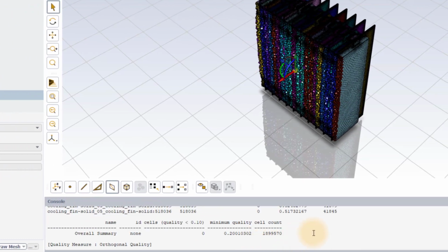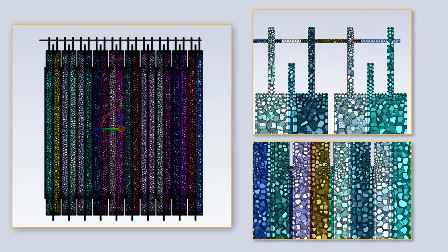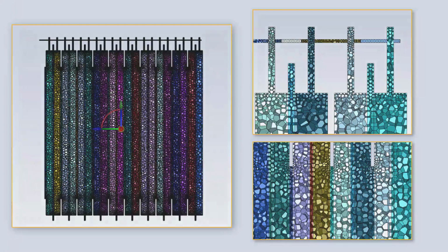The generated mesh has a total of approximately 1.9 million cells with a mesh quality of 0.2. Hence, we have generated a good quality conformal poly mesh, as can be seen from this sectional image, which can be used for performing conjugate heat transfer analysis of the battery module. That brings us to the end of this workshop.